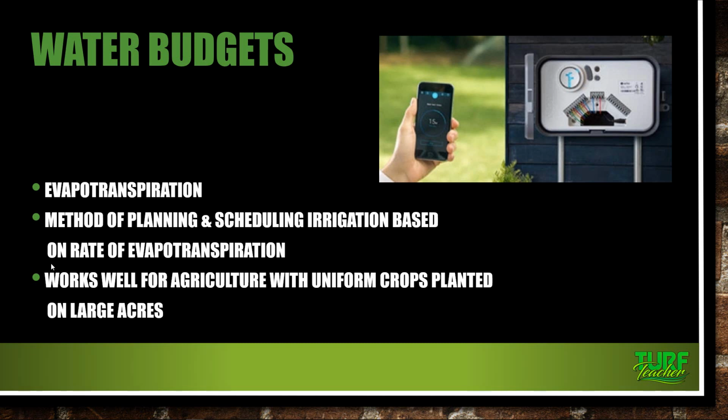But after we get our baseline, then we can establish what our actual LWA, or our landscape water allowance, is for that property. And then we're going to multiply that answer by 0.70. I am off only by just a couple gallons for the month.